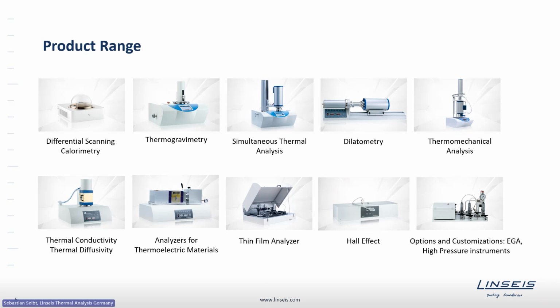Besides that, in the lower line, we also have a broad range for thermal conductivity and thermal diffusivity. On this picture here, you can see an LFA, a laser flash instrument, which is more or less the most famous one because it's universal. And besides that, we have multiple other techniques for thermal conductivity, like wire techniques, guarded hot plates, and heat flow meters and so on.